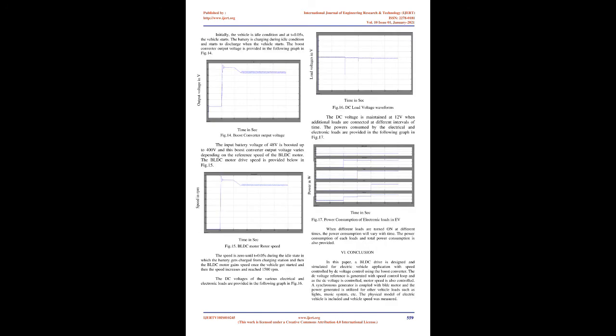The BLDC motor is coupled with a synchronous generator of 20V, 750W so that it can supply the loads such as heater/cooler, lights, wiper motor, etc., without drawing power from the battery, and hence the BLDC motor is left undisturbed. The simulation circuit for the synchronous generator setup is provided below in Fig. 10. Fig. 10: synchronous generator coupled with BLDC drive.